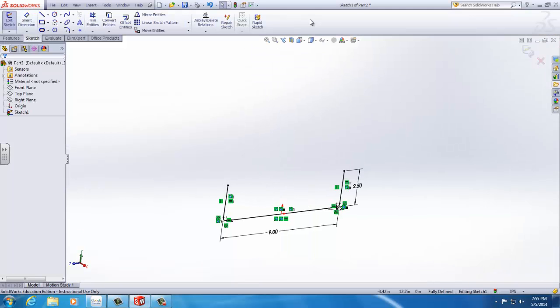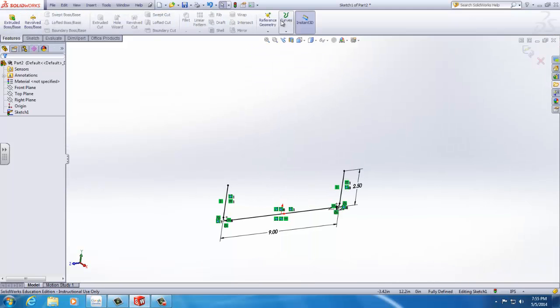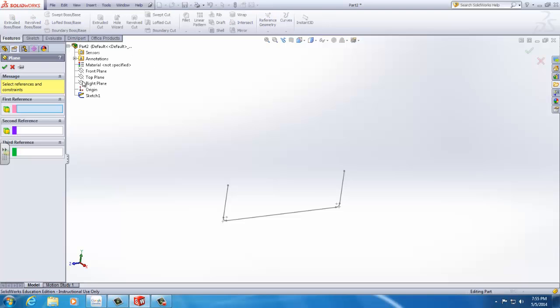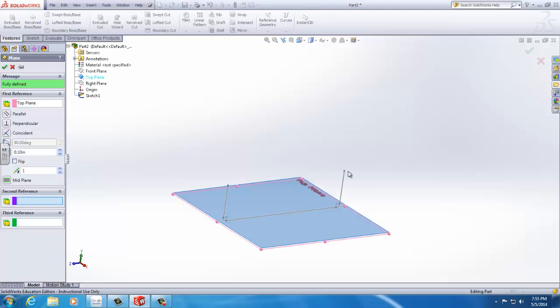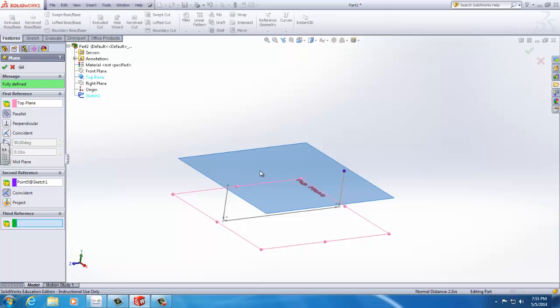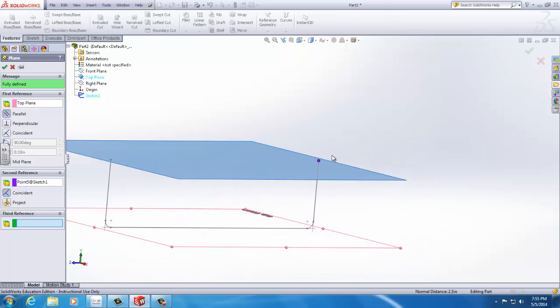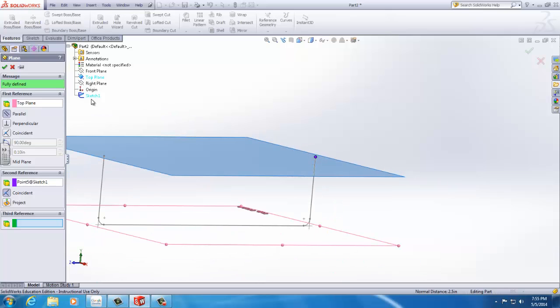Tracing it over, there are two options you can use. Either you can do lines and arcs, or you can use a spline. I prefer using splines. I'm going to use a spline, and I'm going to use one of these points. This is the weird shape I want to trace over. Pretty much you're tracing over. So if we ever change the height, giving it points, the circle location will change based on just that point right there. Click OK.